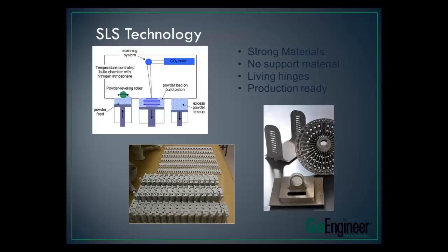It's pretty impressive. Way back when I was in the model shop, we had a part that was brass that was SLS. It was a little bit different because it was actually impregnated with brass after it was modeled. But now with the technology, they can just weld titanium together and metal and stuff like that. SLS is really good for fan blades, things with undercuts, things you might need metal for, or even nylon. I did a lot of battery housings, electronics housings, clamshells. You're able to do living hinges with SLS, so that helps out a little bit.